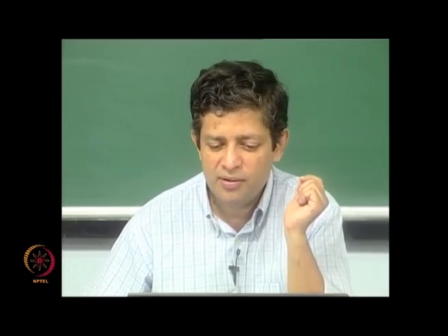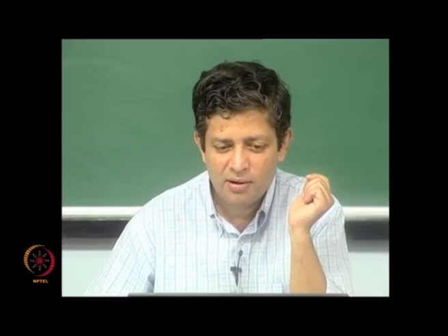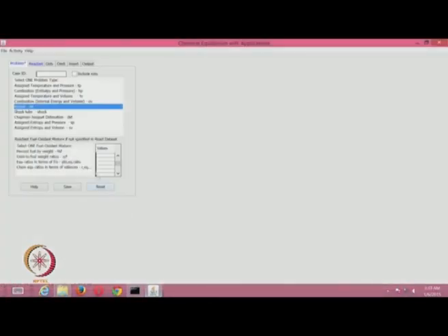Okay. Now, one can also change the aluminum. Remember we said aluminum is added only to enhance the specific impulse. So, let us say we make it 0% and this 86%, so ammonium perchlorate and binder only.